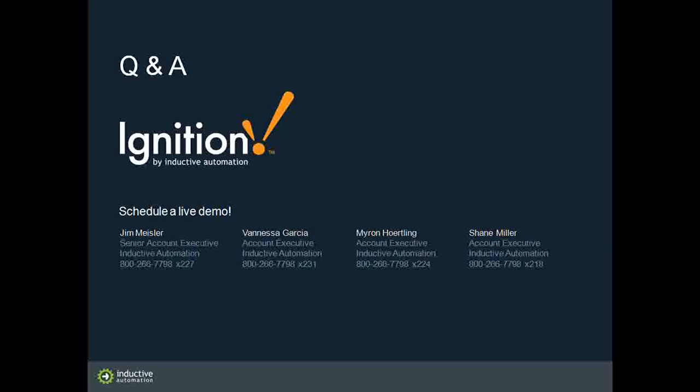This is a question that I'm going to ask both of you. Jason has this question: how does the software connect to the production equipment, the hardware, to monitor uptime, downtime, performance, and quality? Tom, you want to start on that? Yeah. Well, Ignition has a built-in OPC UA server. In fact, they were the first to have an OPC UA server, and I think they're the only one at this time that's cross-platform, meaning you can run it on Linux and Windows.